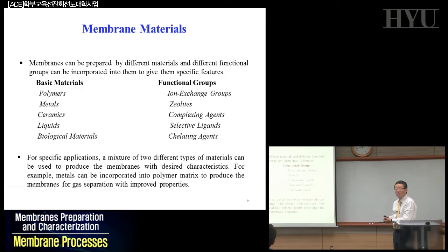You have a crystalline portion and the amorphous portion in the polymers, and it's made of usually organic atoms. The amorphous portions can be utilized for permeation, but remember that the crystalline portion is not permeable, so you have to think about the geometry, and finally the structural geometry is very important for metals and ceramics if you want to use these materials for the membranes.